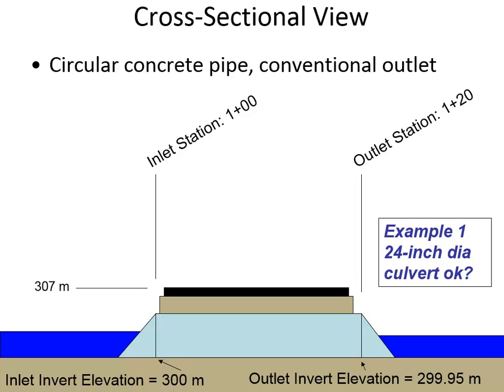Sometimes the specifications for a Department of Transportation or a municipality would say that the water should go through the culvert in a 10-year storm, but a 25-year storm can go overtopping. Maybe it's okay, maybe it's not, but for the program to identify how much of the water goes over the road, it has to know the elevation of the road. So we're also going to enter that information.